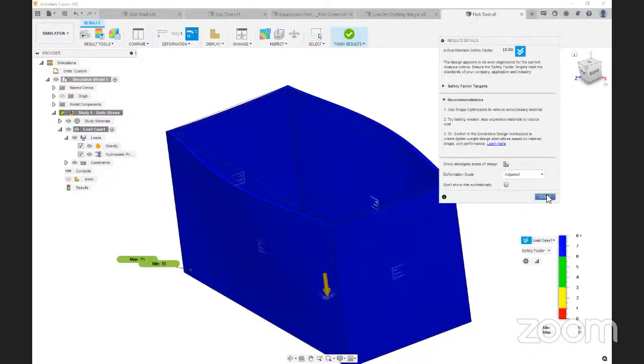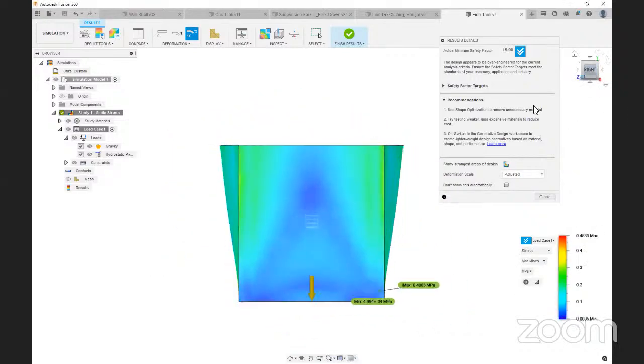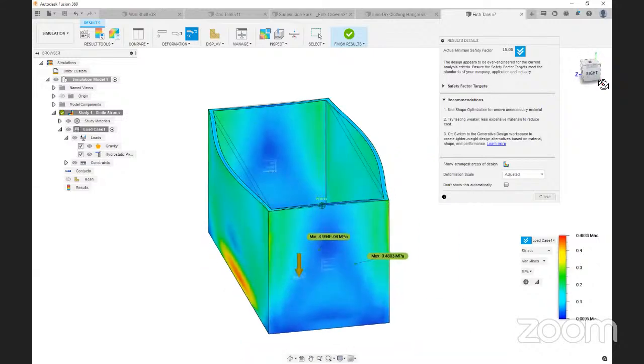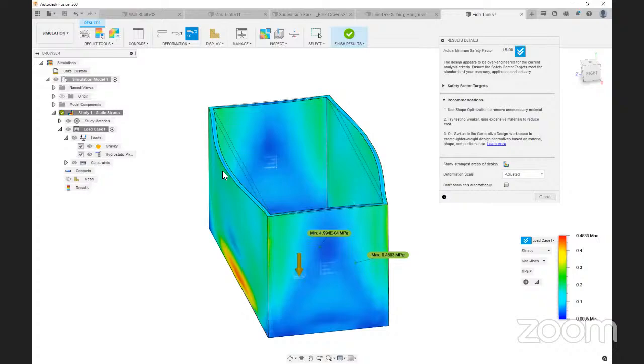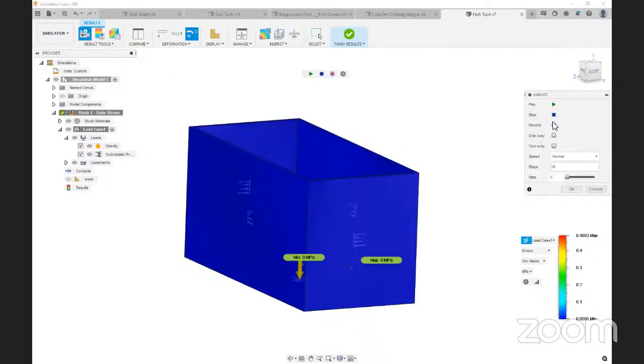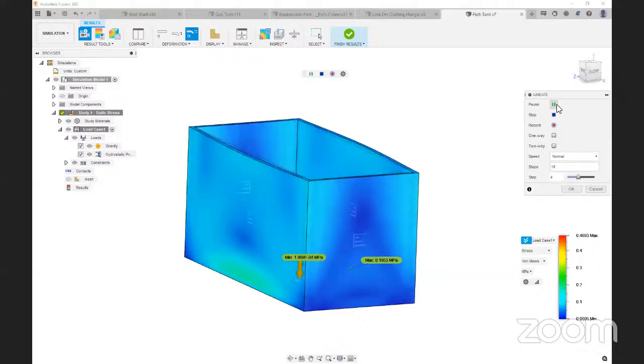And again, high factor of safety. This is adjusted. As you can see here, maybe the high and top parts of it might be more susceptible to stress there. And then you can see most of the stress from the water is actually towards the bottom here, towards the edges there, which is really interesting. Let me go ahead and animate this. It's always a good visualization tool.